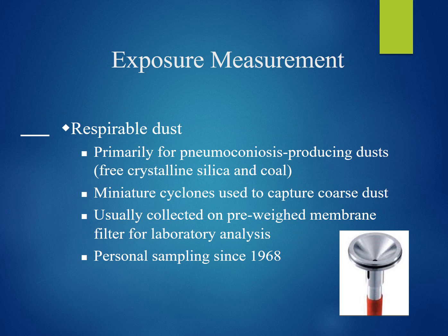To get respirable dust, we use a cyclone. This is of particular importance when sampling for silica and coal dust, because we're mainly concerned with the ultrafine particles, or those that are smaller than 10 microns in diameter.